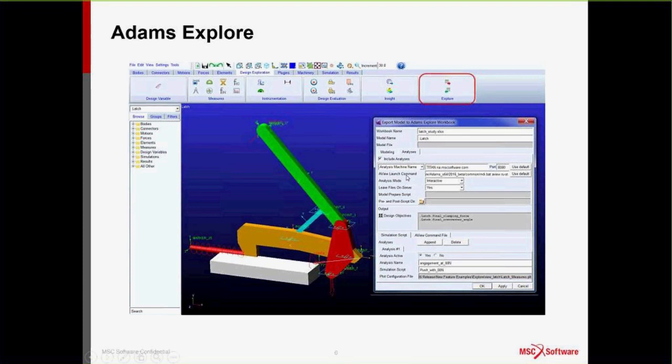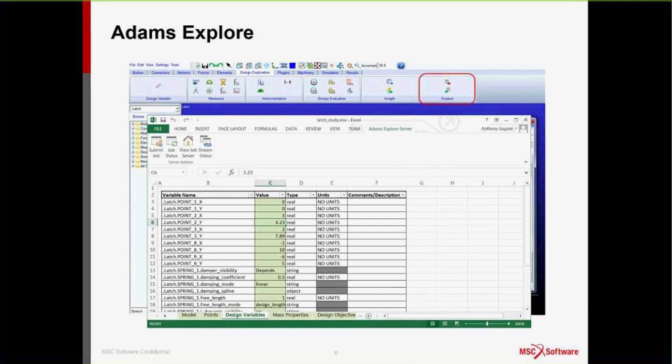And then up here, there's also a capability to specify an analysis machine name and the Adams View launch commands for that machine and for that installation of Adams. And what that does when you export the spreadsheet is it sets up a tab in the spreadsheet where you're able to then launch that machine, assuming that machine is reachable on the network from the Excel user's viewpoint. So what I'm going to do is get into another example showing this from Adams Car in a little more detail, and you can see more about launching runs from the Excel spreadsheet and setting up the spreadsheet.